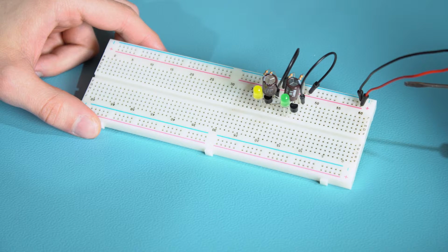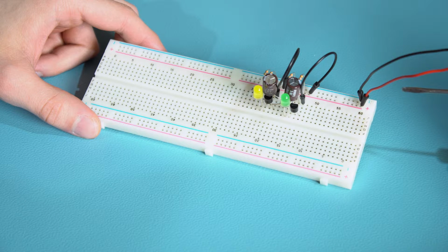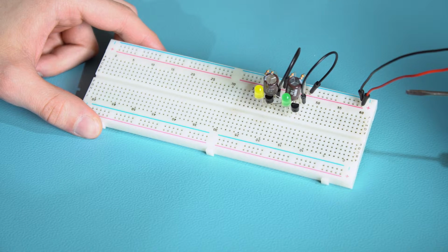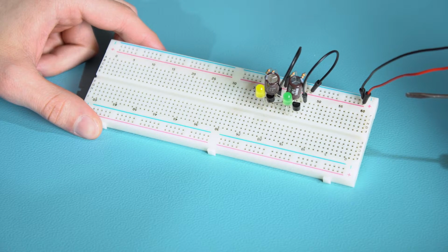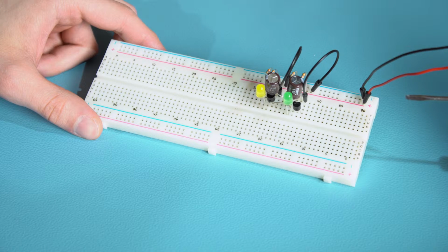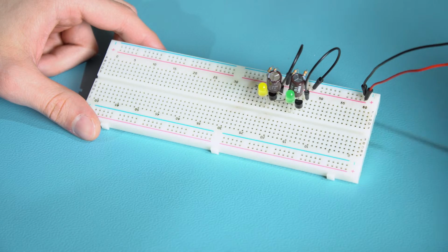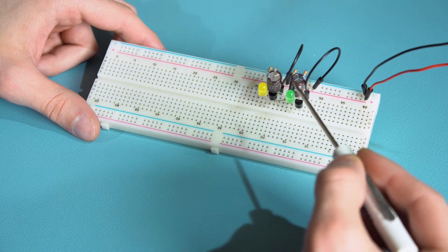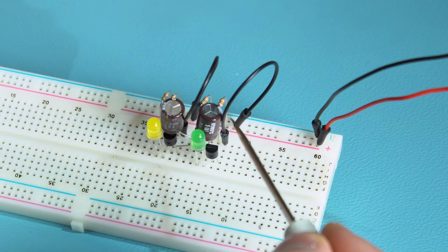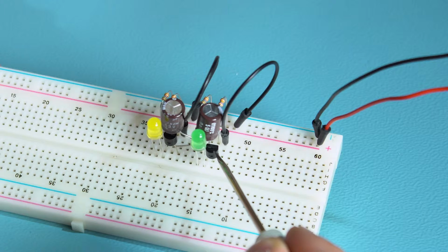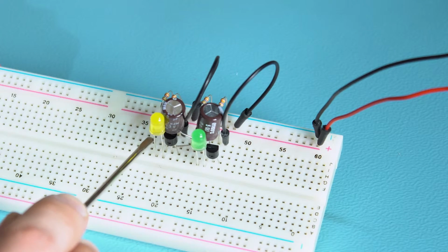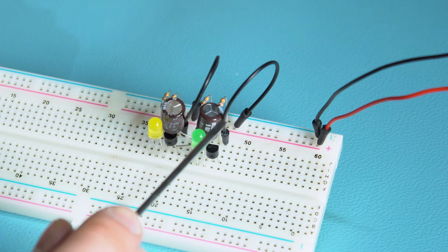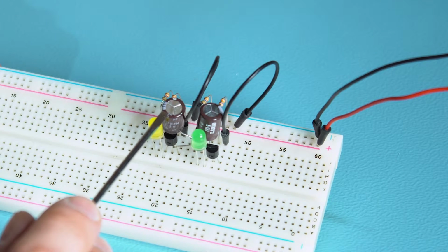To analyze this system, it should be noted that there are no ideal elements and situations. What we mean here is that the transistors are not 100% identical, just as the resistors and capacitors have a certain parameter spread. Thanks to this, one side of the system will turn on faster than the other. The way the system works may be very complex for beginners. Let us just say about it that one capacitor charges when the other one is discharging. This discharging turns on the transistor, causing almost immediate switching of the second transistor, discharging the first capacitor and charging the other, and so cyclically.